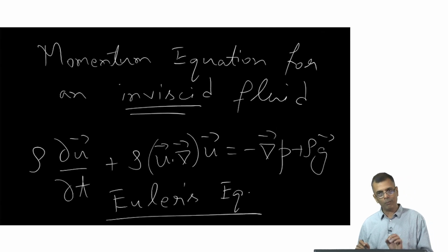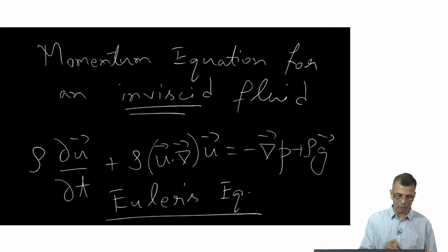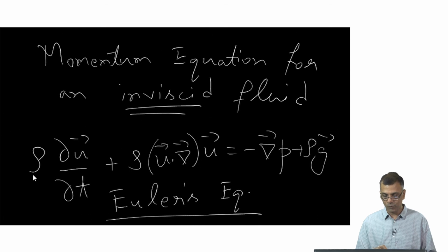It's a bit of a complicated way of arriving at the Euler equation because in order to arrive at it, you also had to use the mass continuity equation. So you arrived at the Euler equation written in the Eulerian frame, in the frame of an observer who is in the lab frame. Hence these partial d over dt's, right?